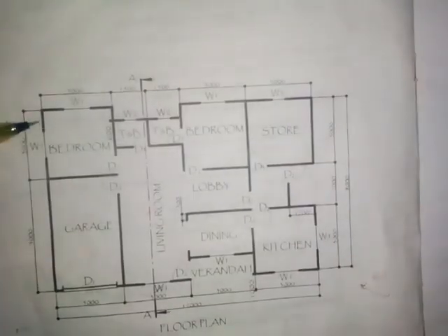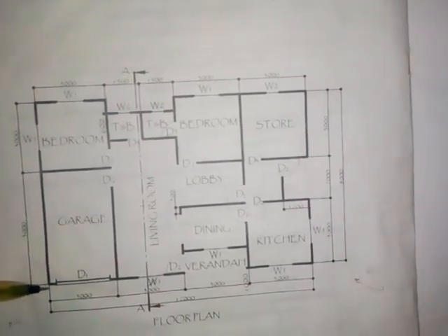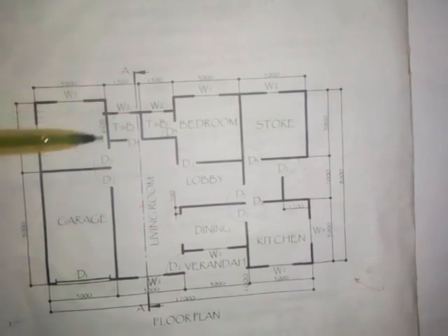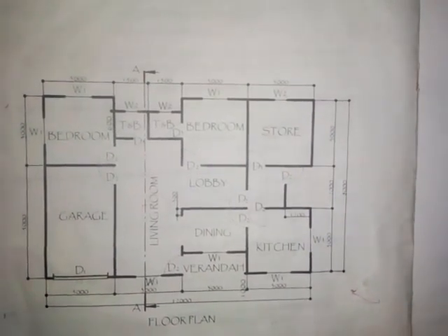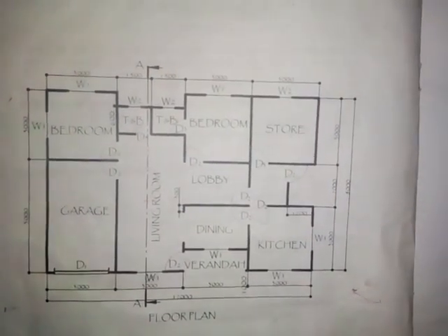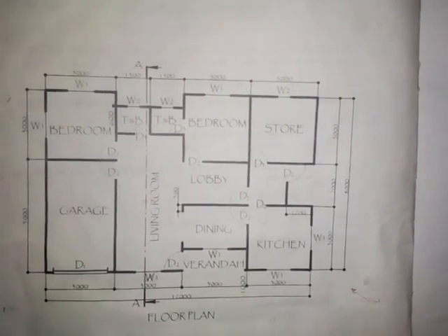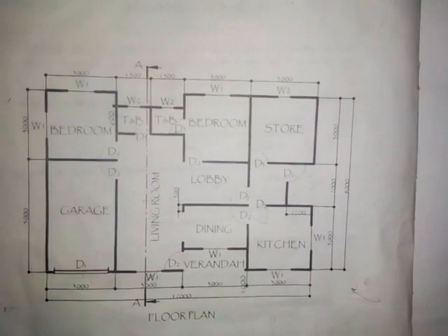So we are going to divide this 8,000 by 50, and that will give us 160 millimeters. So every dimension that we have here, we are going to divide by 50. I believe you can pause the video and see the dimensions very well. You can snapshot it so that you have the dimensions for you to practice. Okay, so let's start. The first thing that I'm going to draw here is the ground level line.